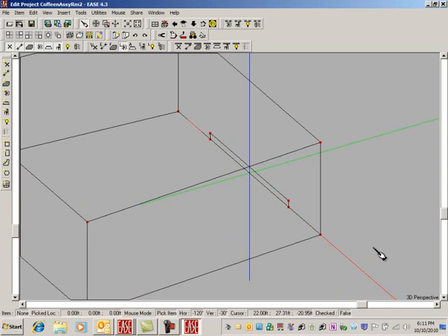Let's look at a plan view to see if it worked right. Oh, yeah. That's in a little bit from this one. Well, as a matter of fact, if we just did an F4 right here, we could see its x-coordinate is minus 20.22 feet. Okay, see what is this one? It's minus 22. So yes, it's in there 4 degrees. That puts these walls out of parallel by 8 degrees to stop flutter echo.